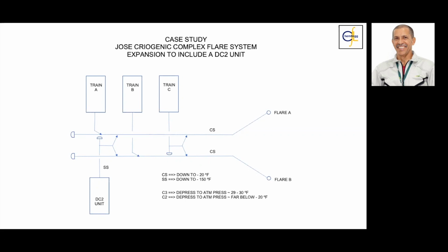The carbon steel, from the point of view of resistance and stress, is very good down to -20 degrees Fahrenheit. And stainless steel is very good to ultra low, up to -150 and lower temperatures, talking about cryogenic conditions.